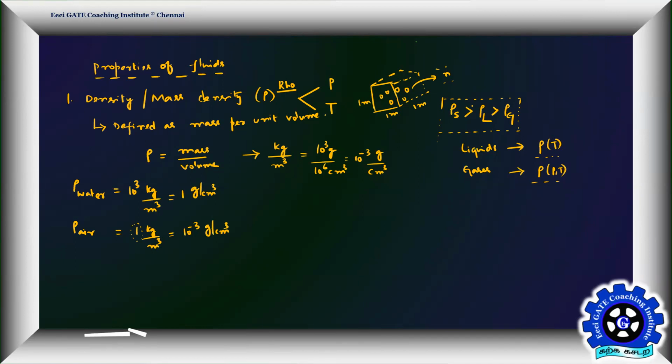But for gases, you have to be very, very careful. Whether you play with pressure or temperature, you have to take into account the corresponding density value in the case of gases. Whereas in liquids, no worry. Only for temperature change do you have to take into account the density value. It's not like extreme pressures you are going to see. For a range of pressures, it's fine. The density won't change much for liquids.